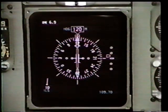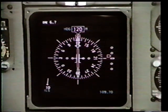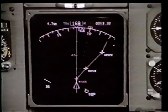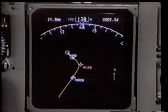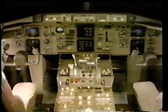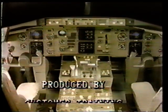The EHSI can present pilot-selectable information in conventional VOR or ILS formats, expanded and simplified VOR or ILS displays, and unique map and plan modes. Selectivity of the CRT information is accomplished through control panels provided for each pilot. This completes this program. You have seen the location and function of each of the major components in the system and have been given a basic description of the system operation.